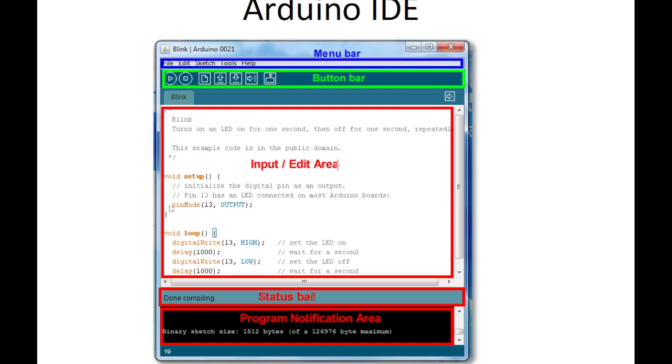Okay, so then after this, because in this setup function there is only one line, once this line is executed the setup function is done, and the program enters the loop function. The first line in the loop function is writing to the port of pin 13 the value high. It means it's writing 1 at that port, which is intended to make the LED go on.